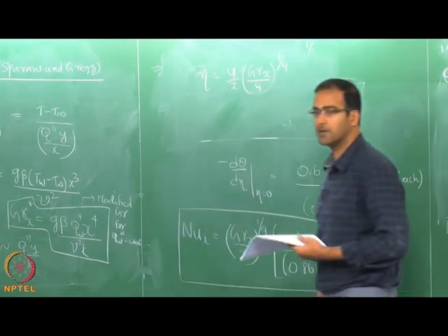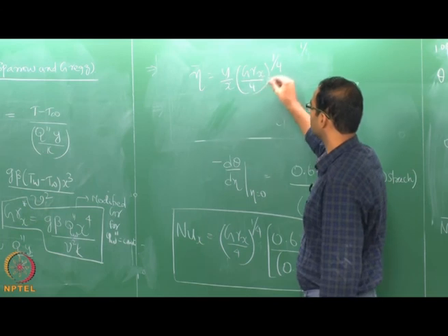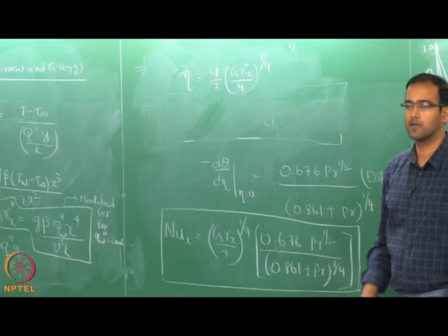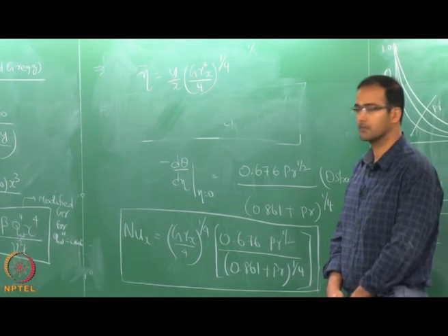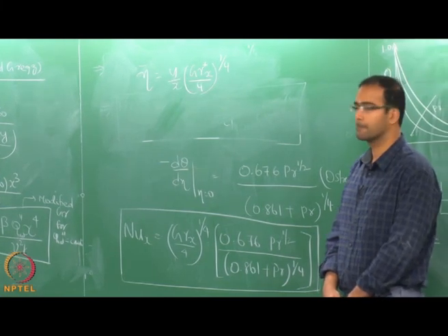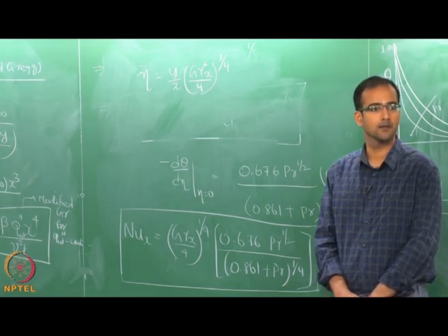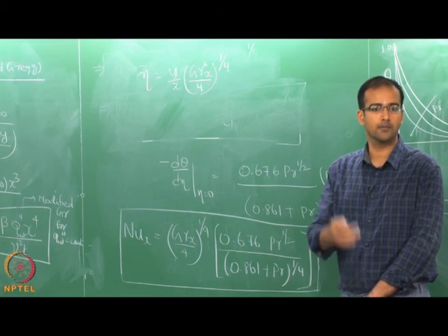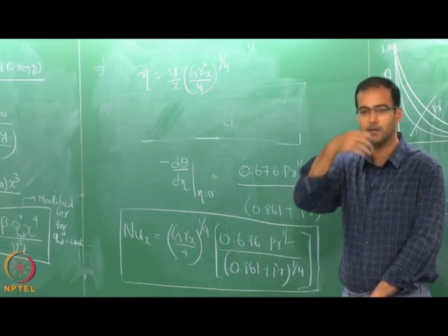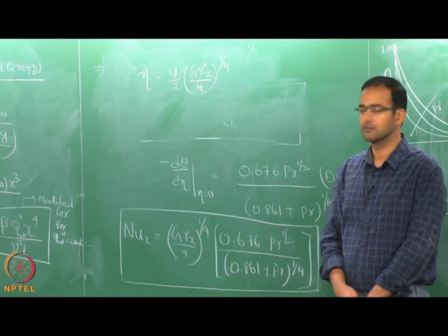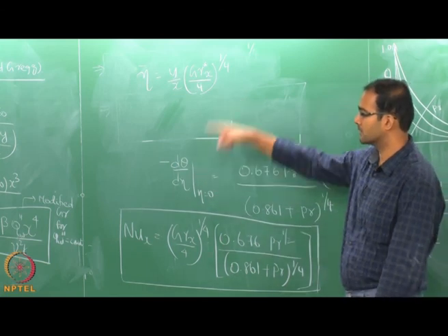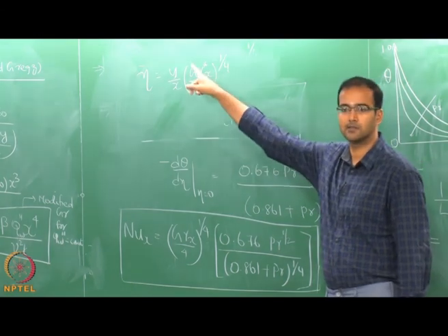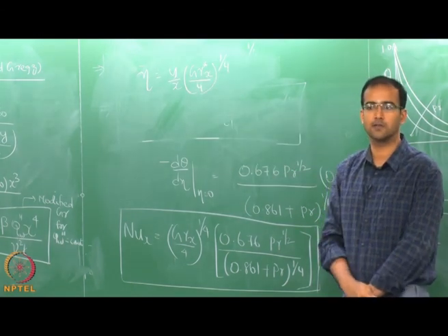Now, if you simply replace this normal Grashof number with Grashof number star, what happens to the similarity variable? It becomes y. So, you will not find the correct similarity variable because there will not be any function of x. Your Grashof number star is x power 4, so x power 4 to the 1 by 4 is x, and x cancels.